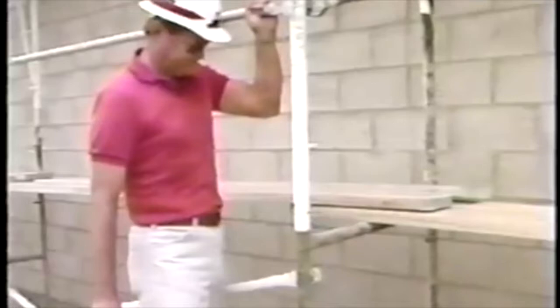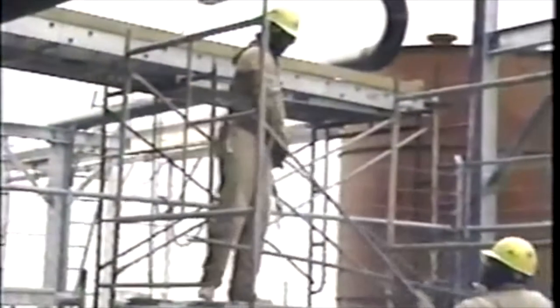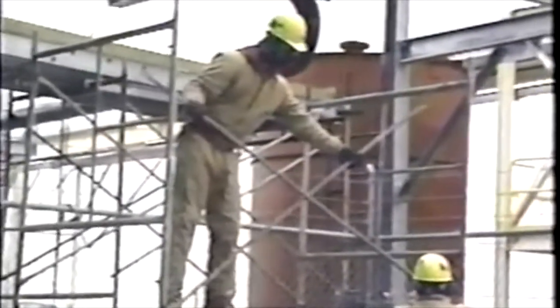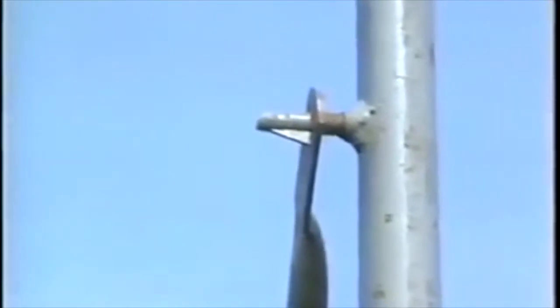When inspecting a scaffold operation, you should check for support under each leg in every frame. Make sure that all base plates are in firm contact with supports. Inspect frames for plumbness. Check frames for gaps and misalignment of adjustment screws. Make sure that all end frames have cross braces to ensure stability and plumbness of units. Inspect locking devices, making sure they're tight, and check all planking for proper installation.